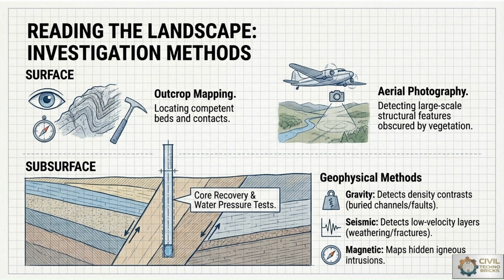Core drilling helps us with the RQD, fracture conditions, and groundwater presence. Geophysical methods identify the weaker zones of the rocks, presence of cavities, and subsurface discontinuities without extensive excavation. So comprehensive site investigation minimizes uncertainty and improves dam safety and foundation design.